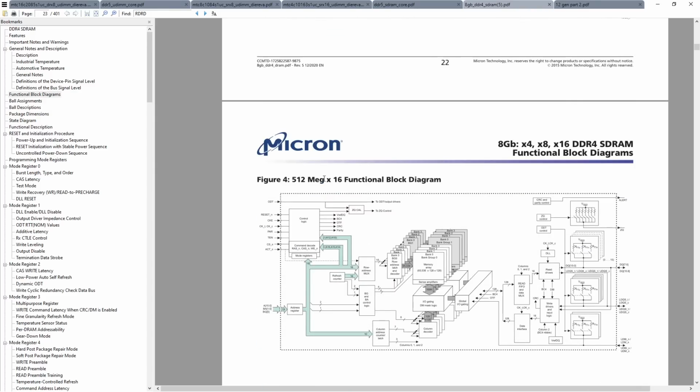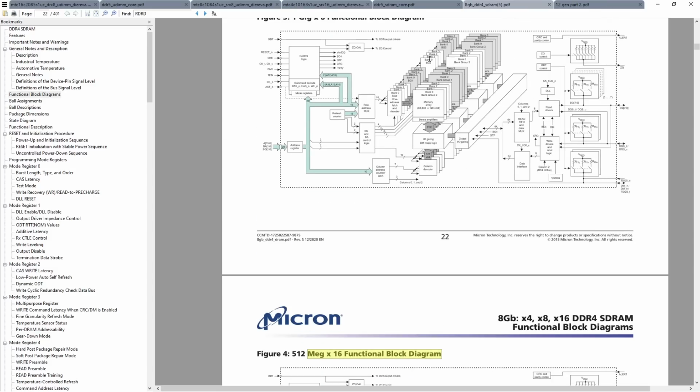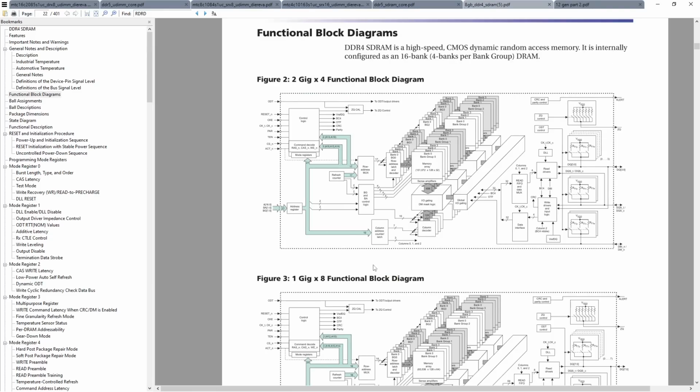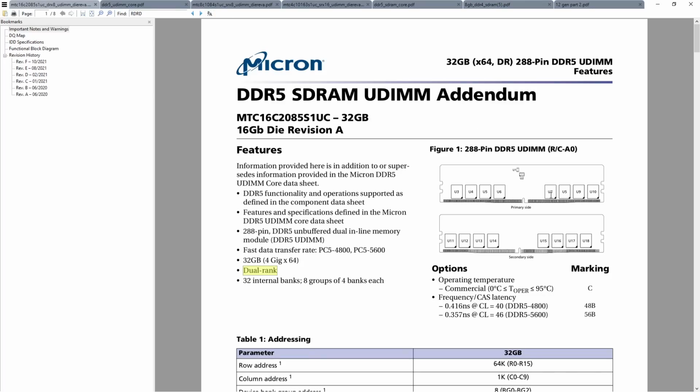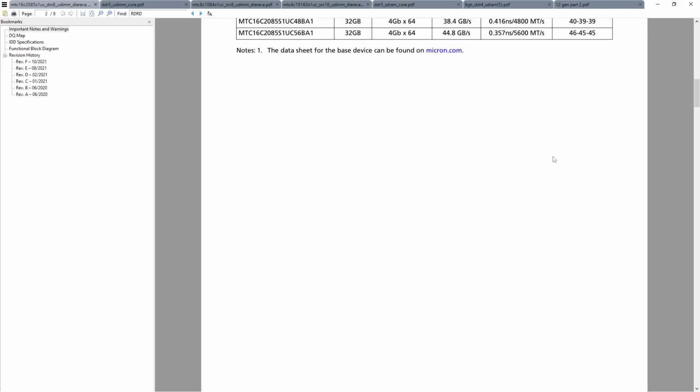And then obviously, if you get your X16 memory chips, those are horrible. You have 2 bank groups, so you're wasting even more clock cycles. That's why these are so slow. But if you have X8 in dual rank on DDR4, that's sort of the ideal for performance as far as I'm concerned, and also from an overclocking perspective, because one of the biggest penalties to quad rank is that it doesn't really improve your performance per clock, and it drastically reduces the maximum memory speeds that you can run. Because it just puts so much more load onto the memory controller, because with DDR, the extra memory chips get connected to the memory controller in parallel.